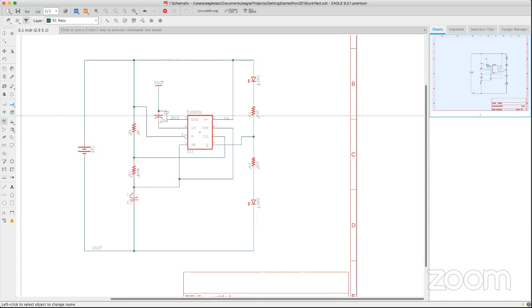So if I have multiple schematic sheets, as long as the nets have the same name, the component will appear connected on the board layout. It's just an aid for you to design a lot faster, especially for those large components when you want to break out all the pins. I hope that takes care of your question, Pep.